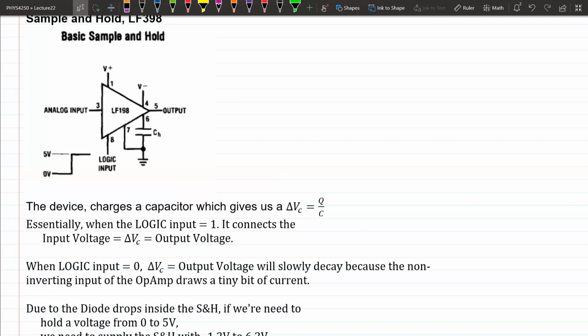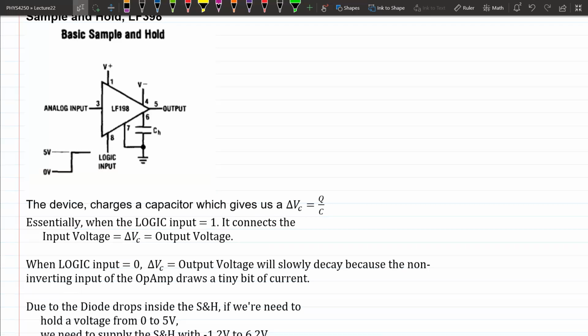And this holding capacitor, unfortunately, since it's not ideal, right? You can't have an ideal system. The voltage on this holding capacitor is going to decay over time. It's going to be known as the droop voltage, okay? The droop of the voltage. So this is another word that we learned in, I think, lab 2, right? When we had the first alternating current lab, okay?